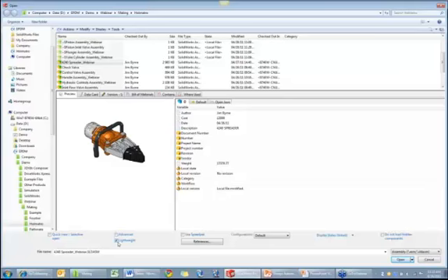Now, I bring this up because a lot of you may be avoiding lightweight because of mates, but keep in mind that you can mate lightweight components because it does have that solid body information available. By the way, using lightweight opens up your assemblies at least 2 times faster, sometimes up to 6 or 7 times faster, depending on the size of the assembly.